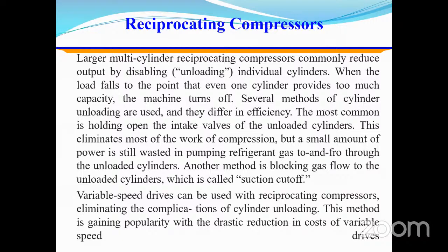Another method is blocking gas flow to the unloaded cylinders, which is called suction cutoff. Variable speed drives can be used with reciprocating compressors, eliminating the complications of cylinder unloading. This method is gaining popularity with the drastic reduction in costs of variable speed drives.